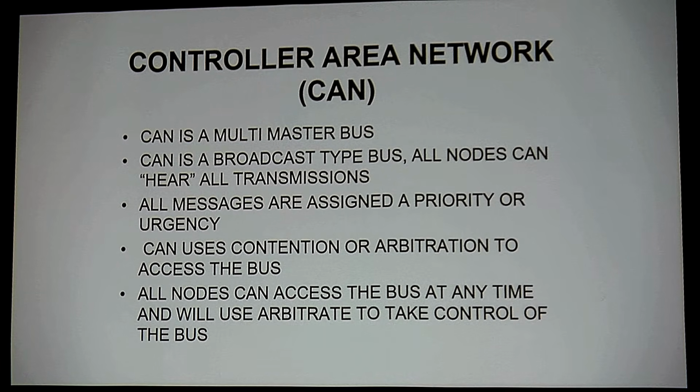So what we do is we arbitrate for the bus. So this is an arbitration, or we fight for the bus. In other words, we contend for it. Each module can come up any time they want, and if we have 5 modules that all come up at the same time, we have to be able to sort out who's going to get the bus. We do this with priority.